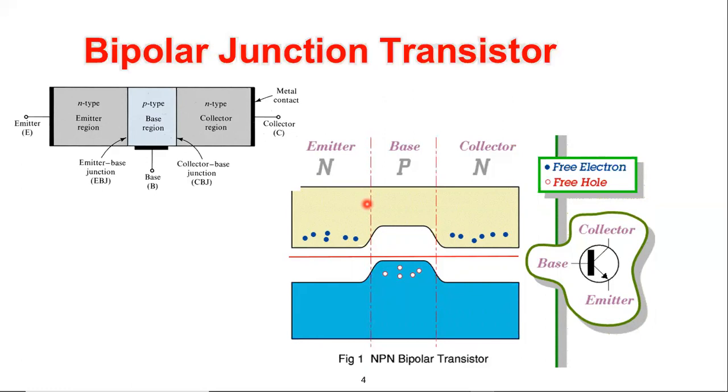Let's discuss. Here we have plenty of electrons, and here we have plenty of electrons, but these electrons are not able to pass to the collector side due to the built-in potential in the PN junction. And here the same, this electron will not be able to pass this barrier due to the built-in potential. The same applies for the holes. These holes are bounded here because, as you remember, the energy of the holes increases going downward. So these holes are bounded, as you see here, by some potential on the left-hand side and some potential on the right-hand side.